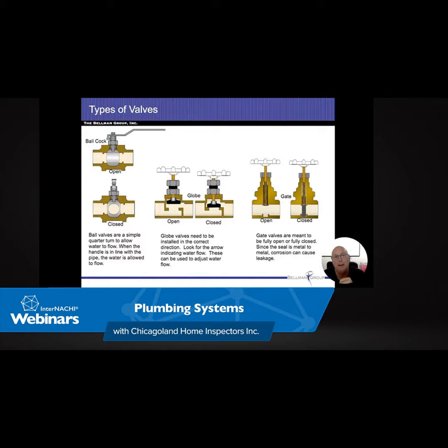So what we can do, and on the right-hand side, they're showing the spigot below the flood rim in that tub. So as I fill the tub, it's going to be filled up with water. Now, if those valves are open, and let's say, again, the fire department comes by and the driver of the fire engine wasn't paying much attention, or maybe somebody else hooked up to it as well, and they can actually create a negative pressure in those water lines. All right, it is possible for that to happen.